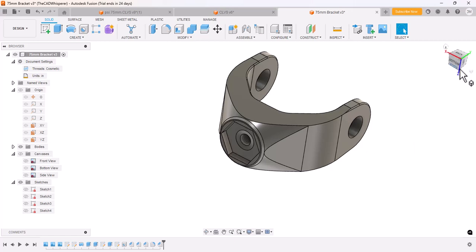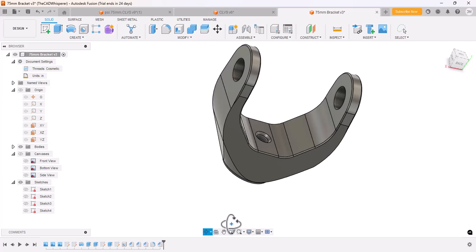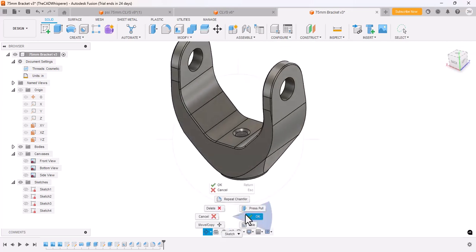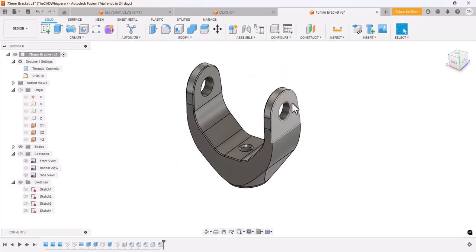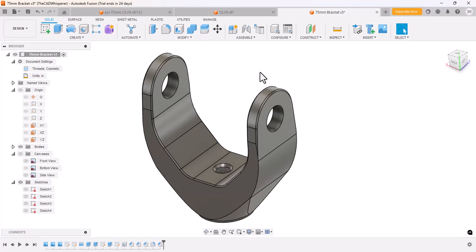All right, so we could do some additional work as needed to get it to match, but I think that the critical difficult parts were these two sides, and this side and the corresponding side on the other side of the part. And I would probably make a configuration of the starting stock and the first two steps, the first two cuts, or maybe a configuration at each individual cut for an operation sheet.